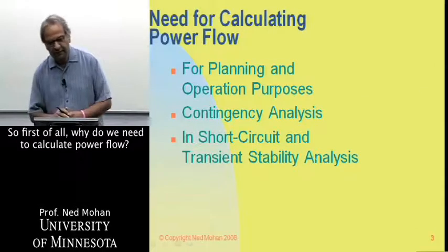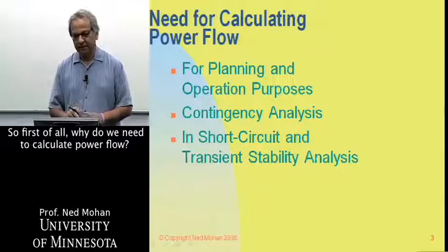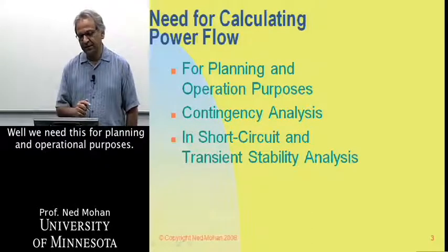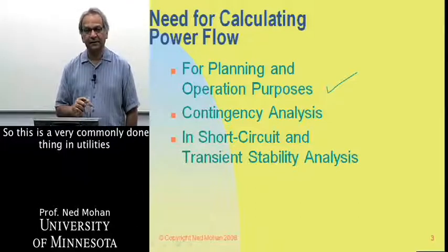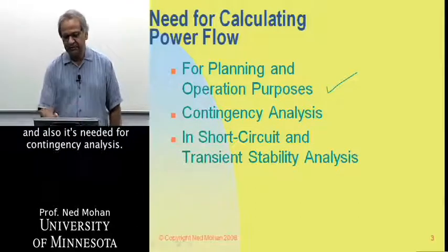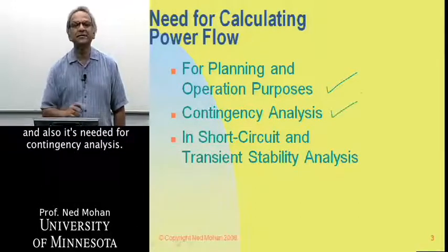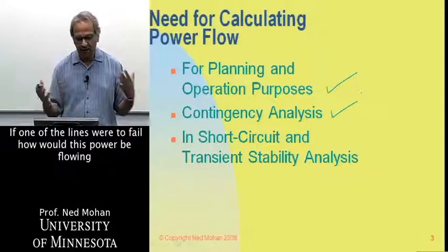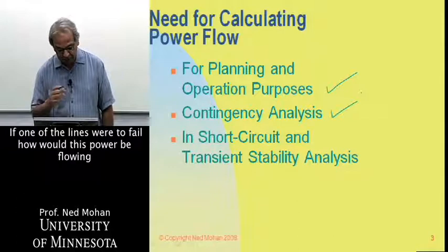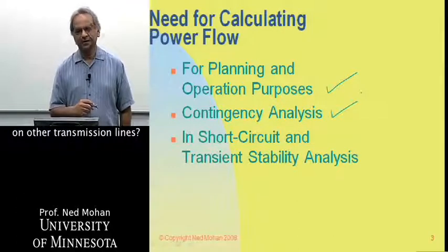So first of all, why do we need to calculate power flow? Well, we need this for planning and operational purposes. This is a very commonly done thing in utilities, and also it's needed for contingency analysis. If one of the lines were to fail, how would this power be flowing on other transmission lines?